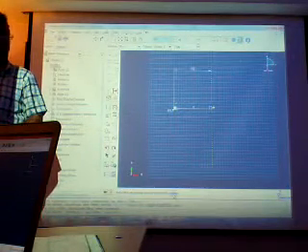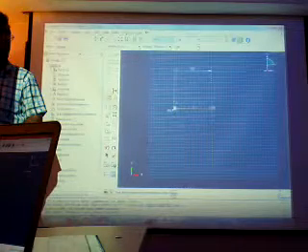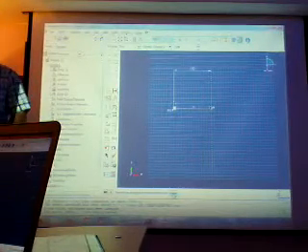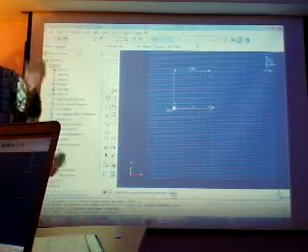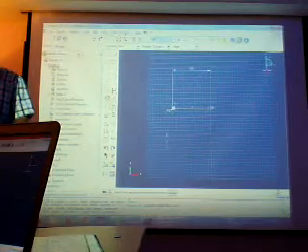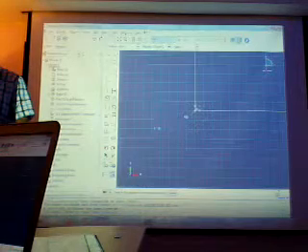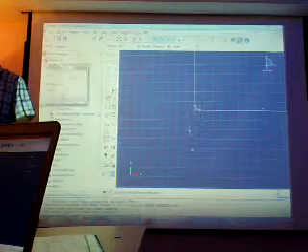I think you need also to take this fillet. If you skip this one, in mesh generation, sometimes we have problems. So take it small, take it one, because normally this should be very small.